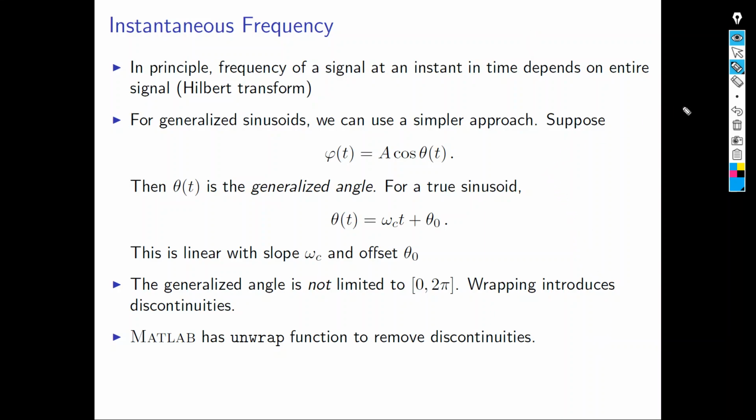Like you have in the window of that device that you can open from a computer or a PC, you have your frequency here, and you have also the power of your signal, the power spectral density, the density of your signal at certain frequencies. So basically sometimes you get signals like this. We call this the power spectral density of your signal. You see your signal in the frequency domain.